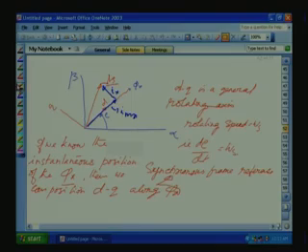So, yesterday we derived the space phasor based voltage equations for the stator and rotor with respect to the alpha beta reference axis, where the alpha is placed along the A phase reference axis. So, alpha beta we call the stationary reference frame. Now, finally, what we want is the instantaneous position of the flux.